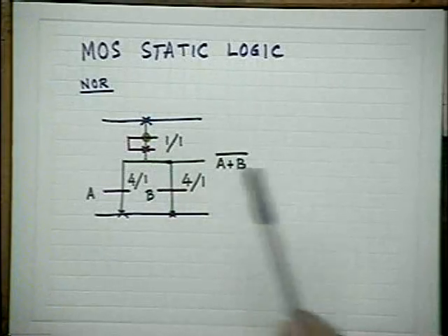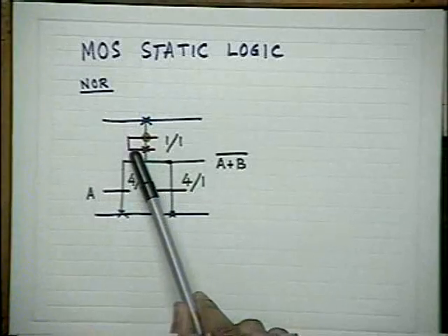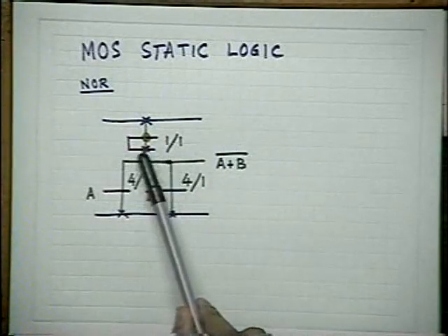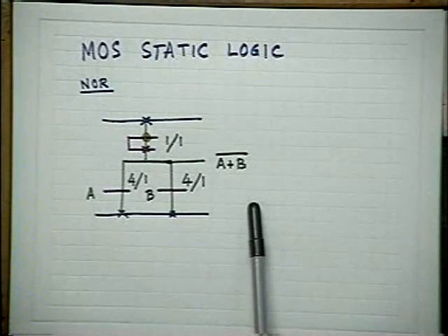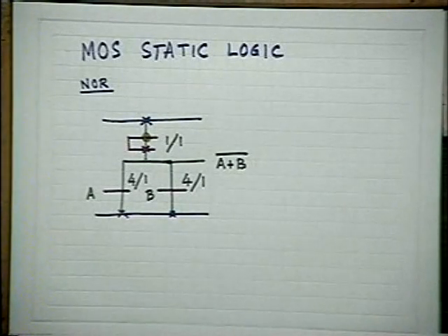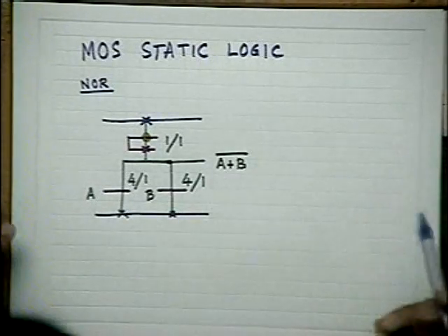In actual technology today, of course, we do not extend the diffusion line like this, because in that case the capacitance of this diffusion line will be too high and there will be a lot of delay involved. So what we do normally, from this point, there is another metal line with a cross, which I indicated in the last class, which goes to the input of the next stage. This metal will have a cross cut with a similar poly line in the next stage. And in the conventional way, which I will prefer to draw in this class for your convenience, you don't have so many colors.